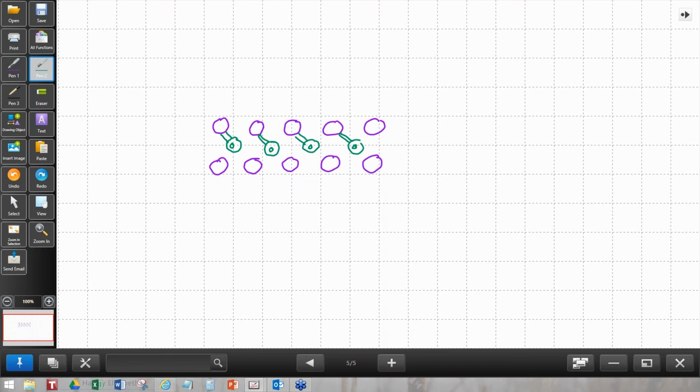That way, a surface mount pad doesn't have to worry. It can be surrounded completely with solder mask, and the surface mount pad won't lose any of the solder allocated to its ball. That works really, really well. But you have to make sure that the solder mask is adequate to prevent the solder from wicking from the ball into the hole of the via. So this is oftentimes a very, very tight space.